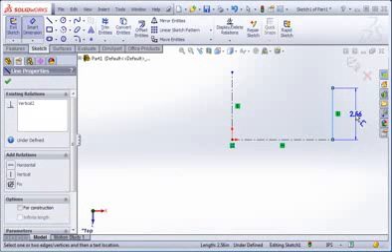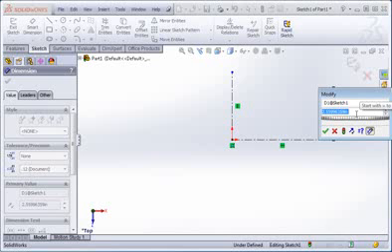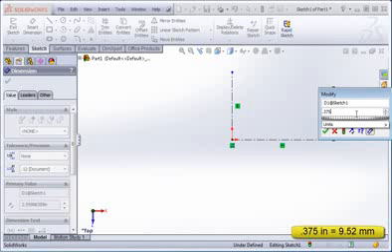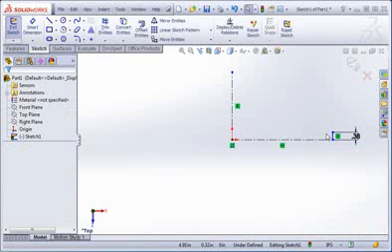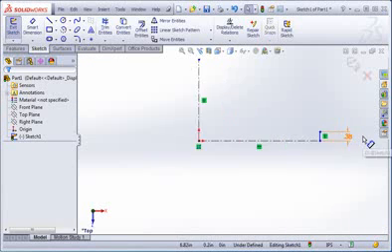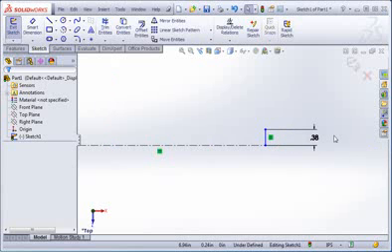and then click the line. Set the length of the line to 375,000ths of an inch, and then click the green check. Now type the escape key to exit the command. The units are set to 2 places, and this is one of the things we're going to fix on our template. Typically, mechanisms and mechanical devices use 3-place units, so let's change this setting.